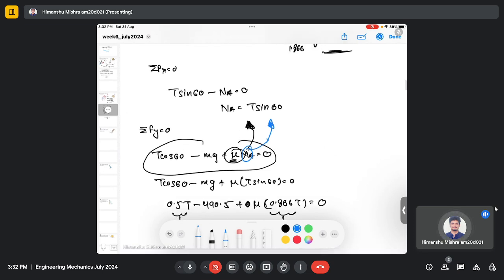So this is the usual trick: you need to write down all three equilibrium equations, two force equilibrium equations and the moment equilibrium equation, figure out what the unknowns are, and try to calculate them. You have three equations, so the unknowns should not go beyond 3. This is one of the restrictions of the equilibrium method that we discussed very briefly in the virtual work tutorial.